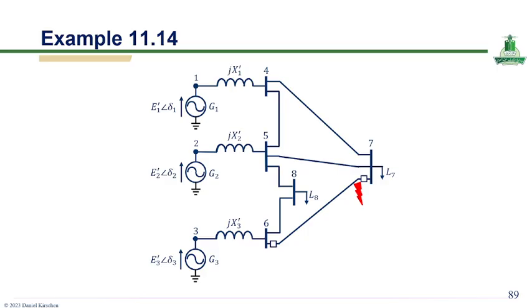This example serves as a basis for applying the previously developed swing equations and numerical integration method to study how rotor angles and speeds evolve and to assess whether the system remains stable or loses synchronism following the disturbances.